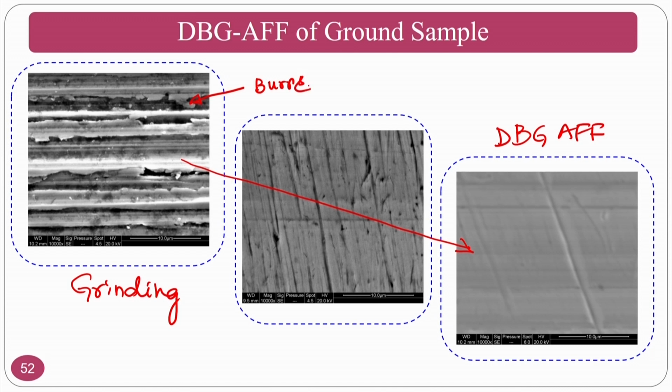Okay, these burrs are there and some of the debris, some ploughing is there, because whenever the abrasive particle is moving here, there is a smearing of the material, or deforming the material towards the next one or the previous one. Okay, from this slide what I mean to say is the importance of polymer assisted abrasive finishing processes, which is this particular course.